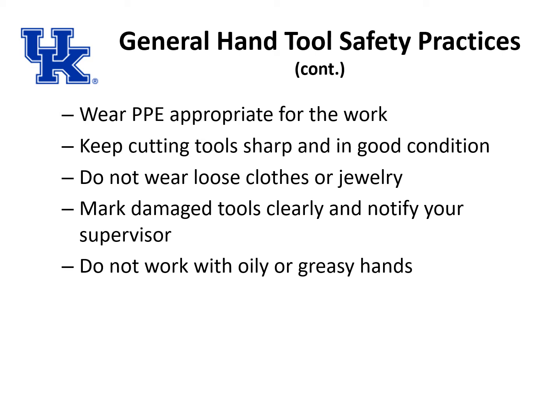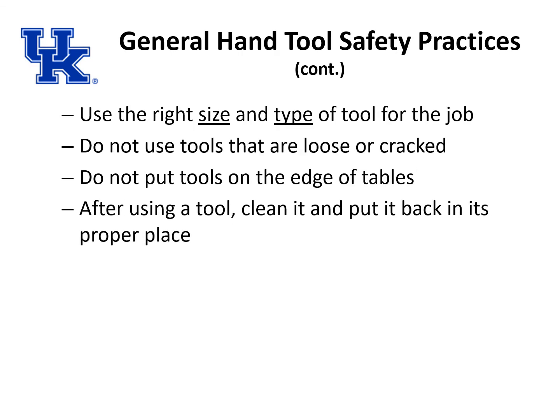Do not work with oily or greasy hands because you are likely to lose your grip on the hand tool, which could result in an injury. Select the correct tool for the job and make sure it is the correct size needed for the job. Do not use tools that are loose, cracked, or otherwise damaged.